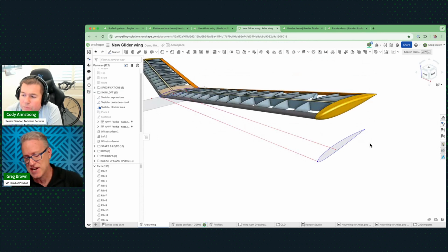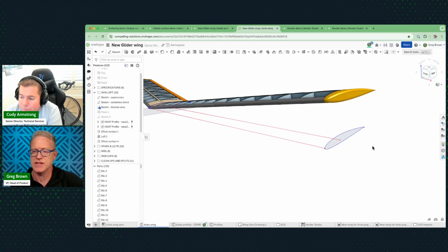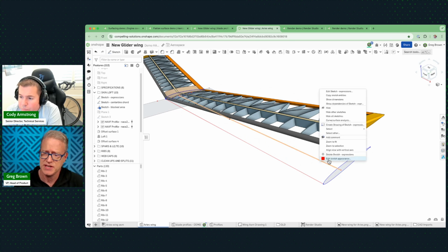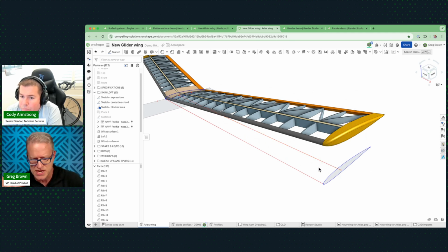These little things add up when you do this multiple hours per day, every week of the year. And we are very focused on these types of things. Also, with colors, you can see here that I've assigned colors to different sketches. I have my own nomenclature: primary blue is for a primary sketch. Red is for projected sketches and things like that. You can come up with your own intent in here.